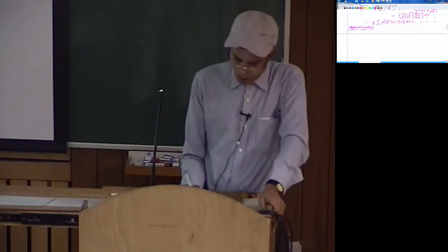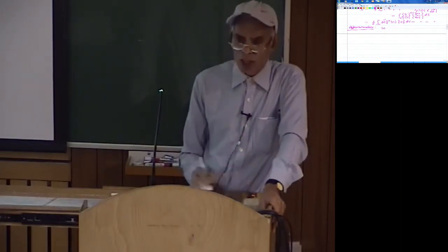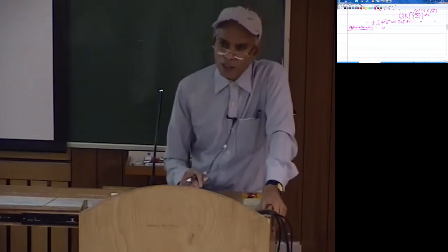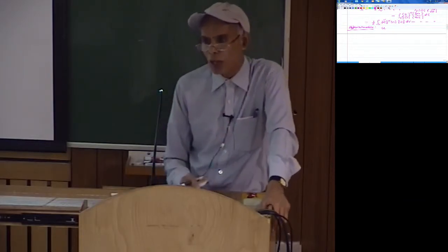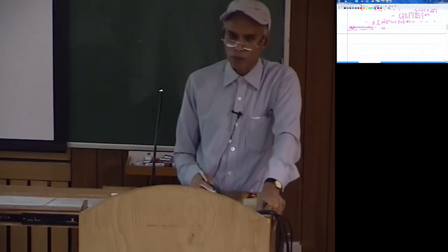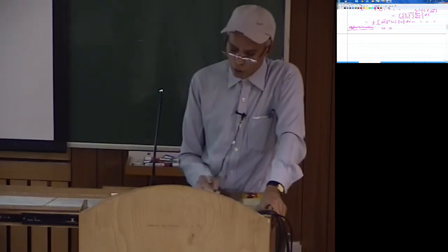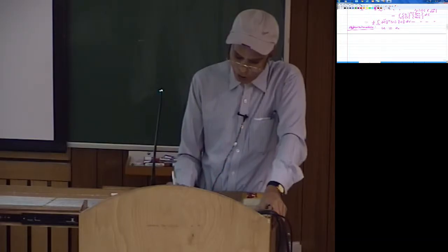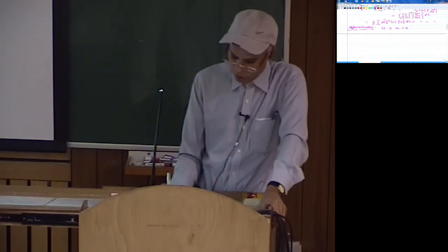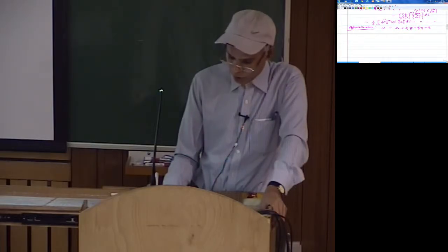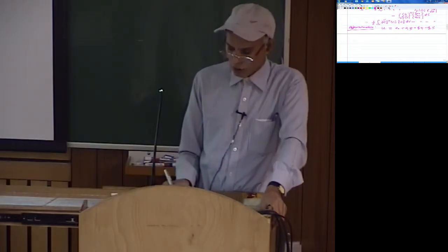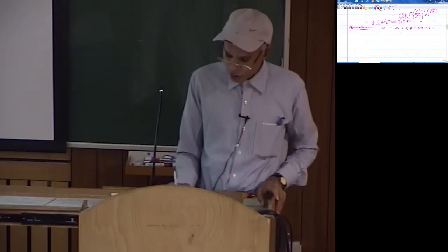Now as far as the approximation is concerned, we would like to assume u, and again to satisfy the inter-element continuity requirement for all general parallelepipeds in physical coordinate space, we assume this in the natural coordinate space. So we have a constant term A0 plus A1 xi plus A2 eta plus A3 zeta. These are all linear terms, and then the bilinear terms.